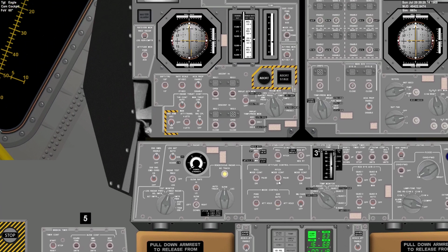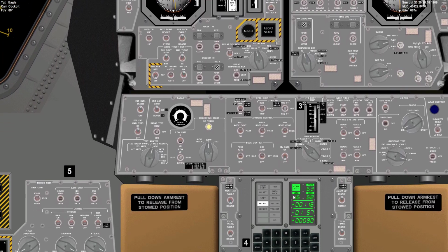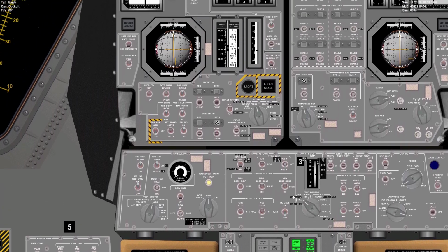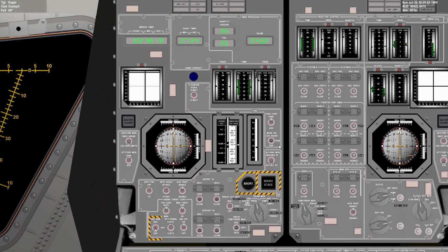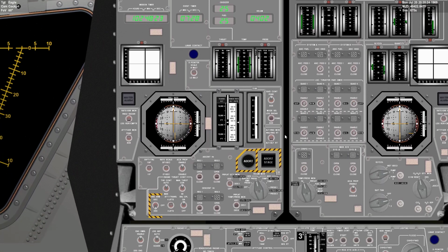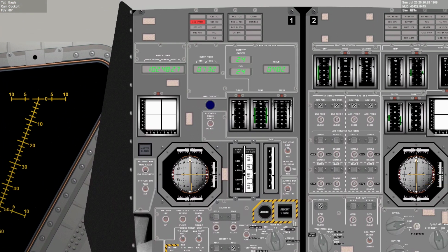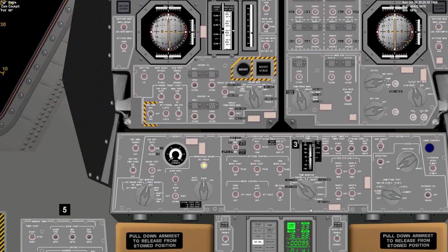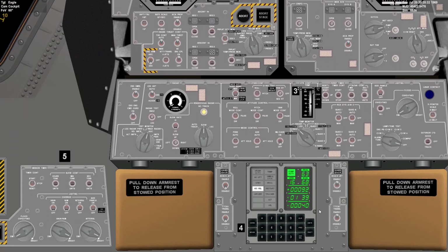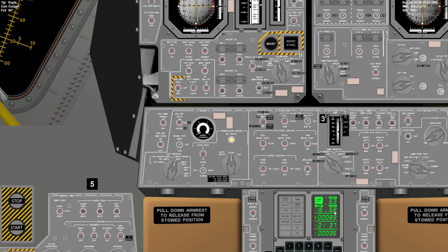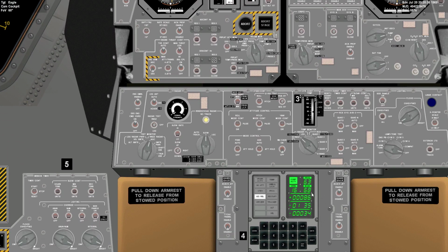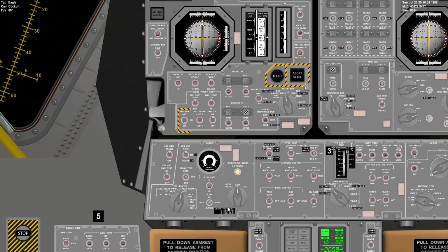So if I were to go from this screen to looking out the window, I might get a bad landing radar reading, which would send the LEM off at a crazy angle. In late P63, after the throttle down, that's pretty catastrophic. That can just lead to a crash if that happens once. So I'm just going to stay in this view until we get into P64 and pitch forward, and then it's safe for me to look out the window.